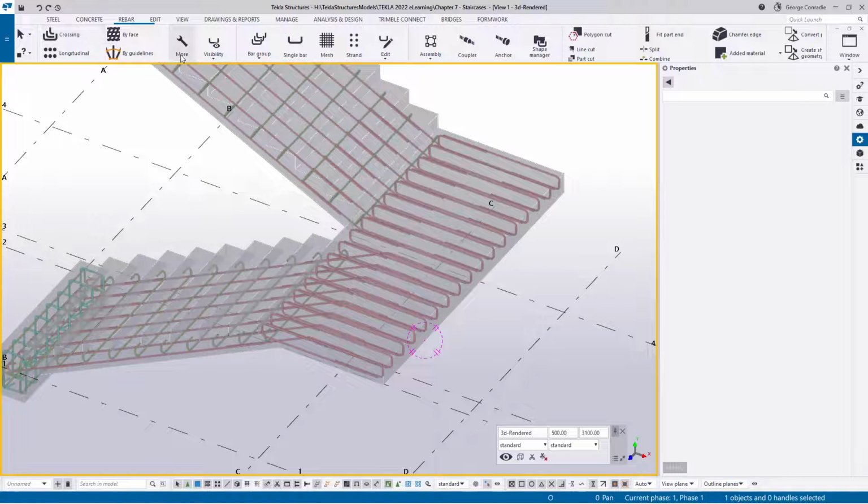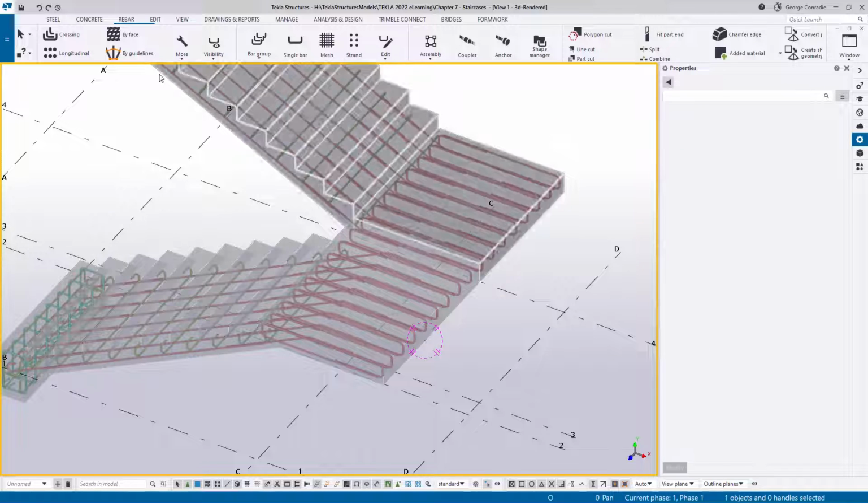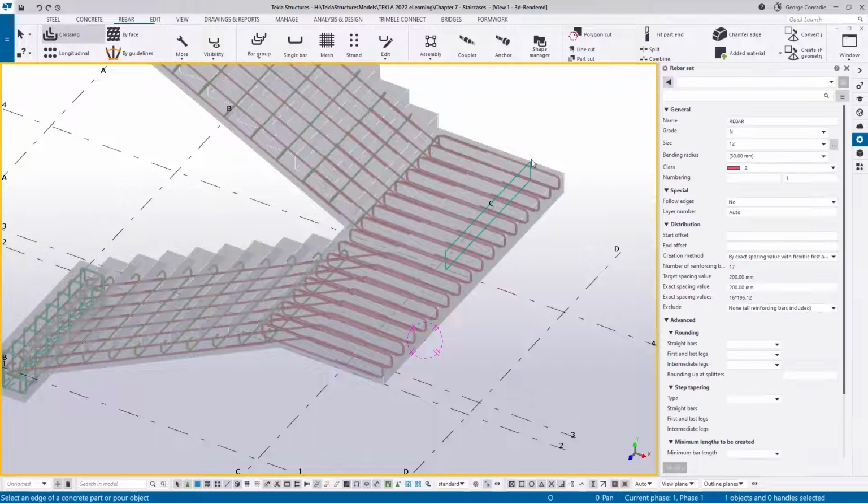So we'll go more point input, and let me first show you what happens if you put in a cross. If you go a crossbar, you can see there, because we modeled it separately, you're not getting your full section. Even if you say, okay, I'll stretch the faces, we're going to have a problem. It's going to try and generate bars that look like, yeah. And when it gets to this point, you see how the bars increase. So it wants a tapered range, and you're going to get an error in a bar. So it's not advisable to use that.